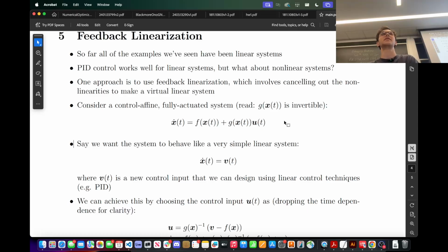You don't need a perfect model. Feedback is going to do a lot of the heavy lifting, feedback being the PID controller, especially underwater, because underwater is a very benign environment to control. So we do a lot of bread and butter style controls. We don't do reinforcement learning. There's zero need to do that. MPC is something we want to do in the future, and trajectory optimization is another. But a lot of the skills that I have seen and used here are the same types of control techniques that are used in actual industry. So it's pretty applicable stuff.